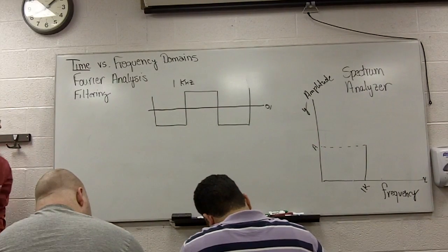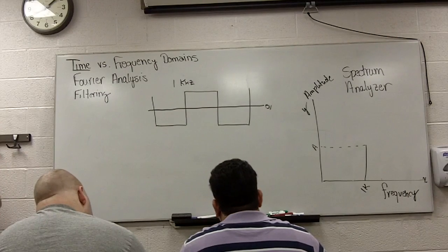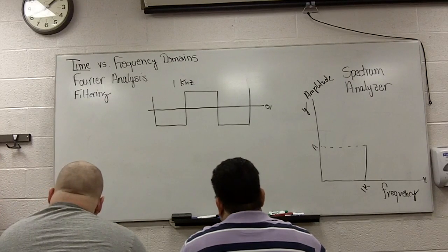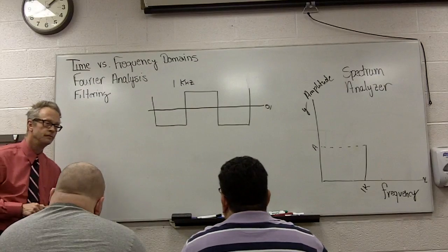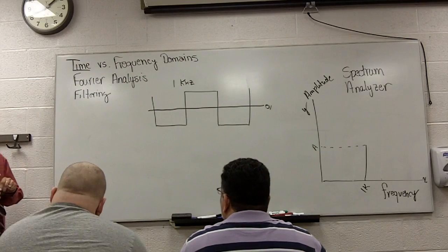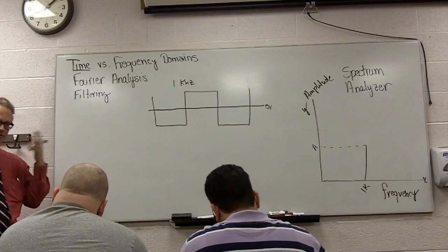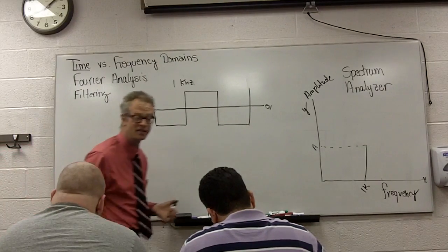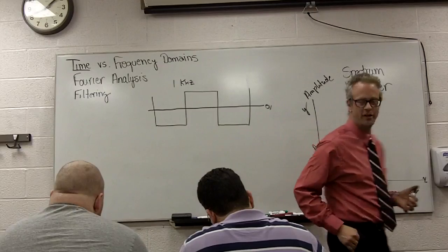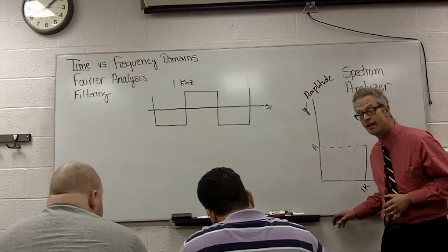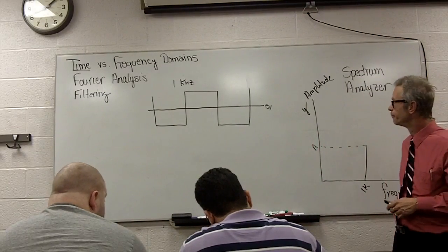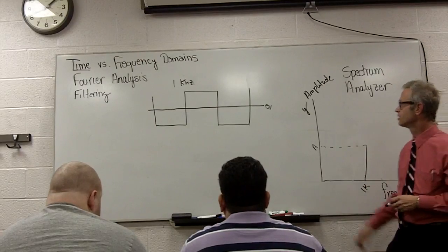So 1 kilohertz is really a good test signal, especially for audio types of things. It's good because you can hear it, and it is not so high that it gives you a headache to listen to. It's fairly pleasing. So we'll pick 1 kilohertz.